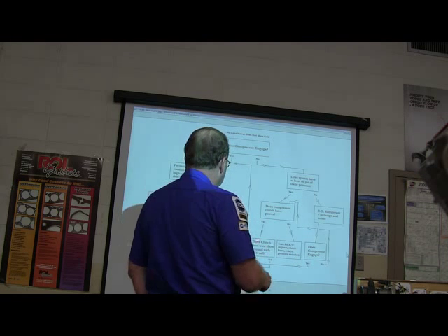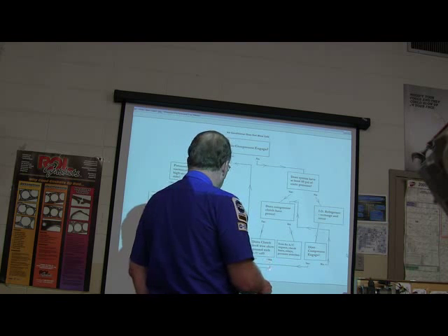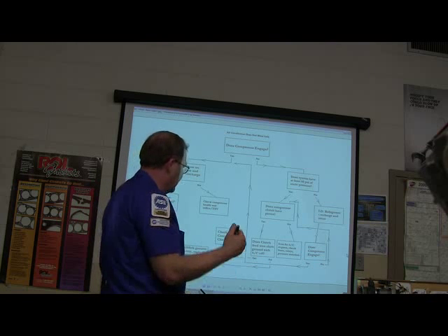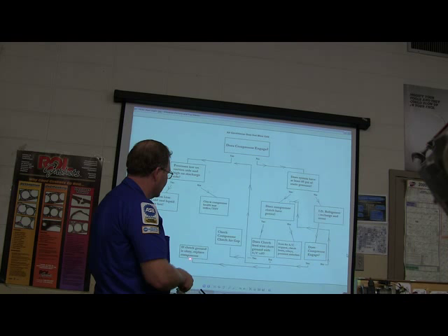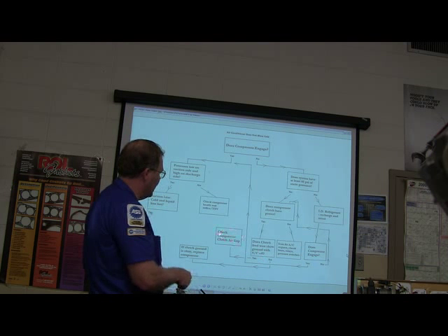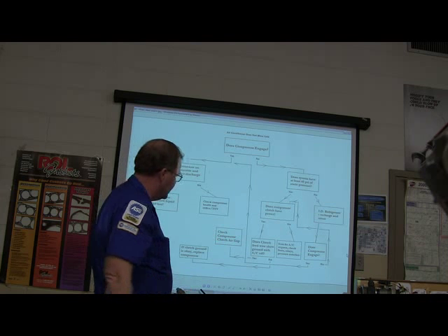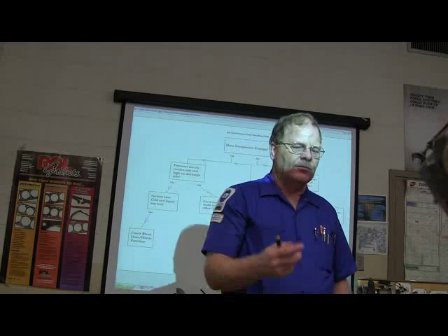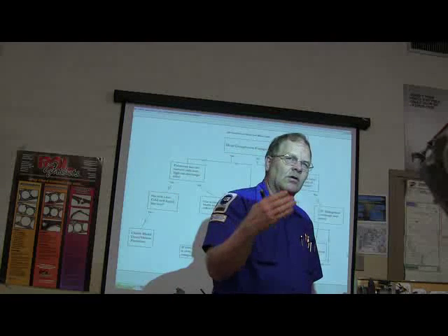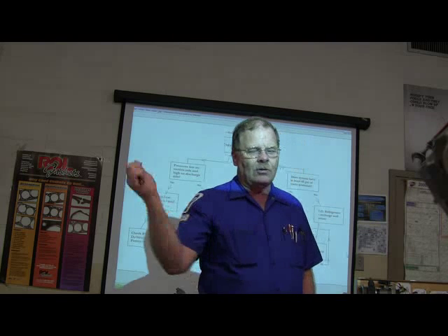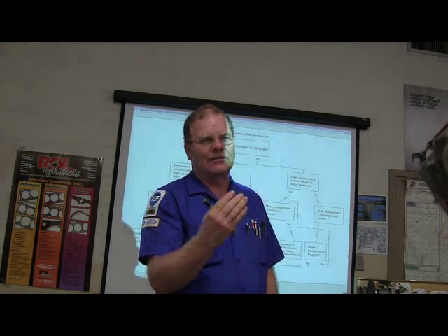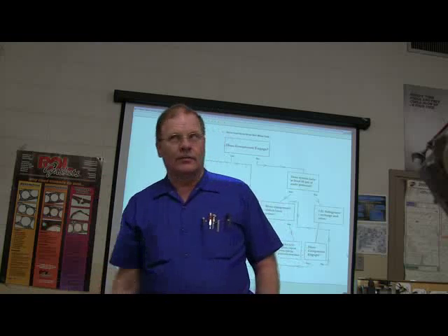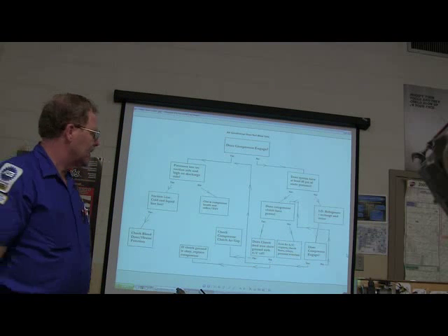On this one here, does the clutch feed wire show ground with AC off? No. If the clutch ground is okay, in other words, the ground that's feeding the clutch, if it's okay, but you don't have ground up here and you know your circuit's good, then you replace the compressor. If there is power going down there, and there's a ground that it shows, check the compressor clutch air gap. What you're going to do there is, with the compressor turned on, when you know it should be running, these will really start out running, and then as they click off and on a few times, they'll click off, but they won't click back on. And you whack the compressor clutch with a screwdriver, and if it kicks in and cools until the next time it cycles out, you know your air gap's a little too wide, and that needs to be adjusted. Different procedures for different cars, but a lot of them have shims you put in there.